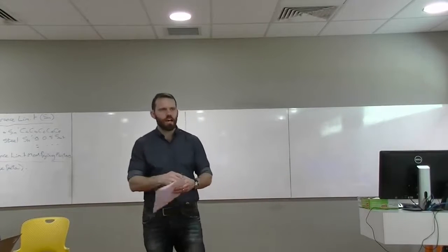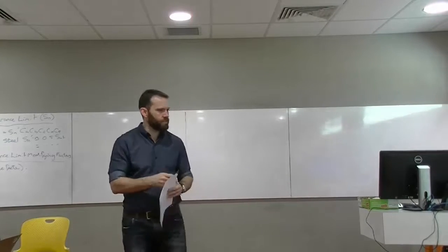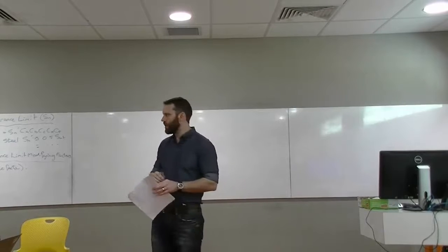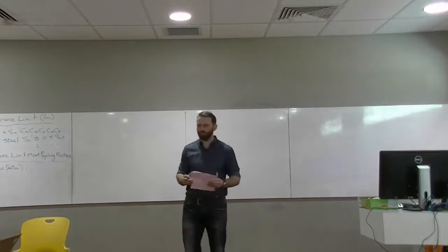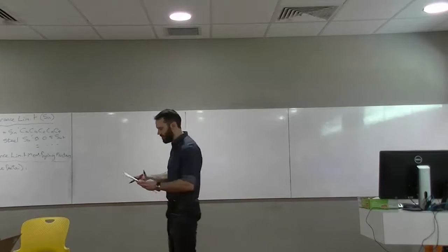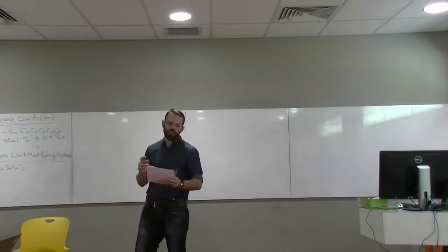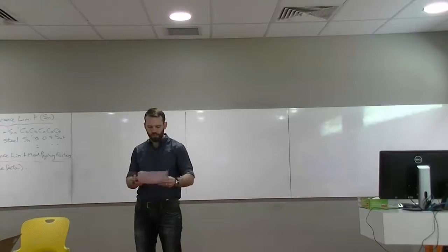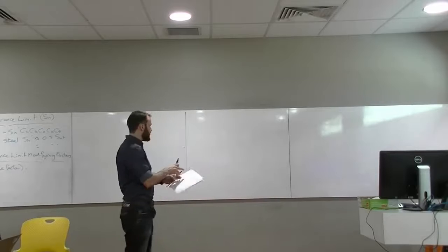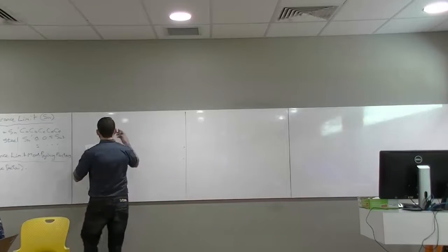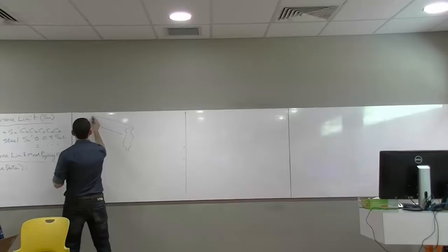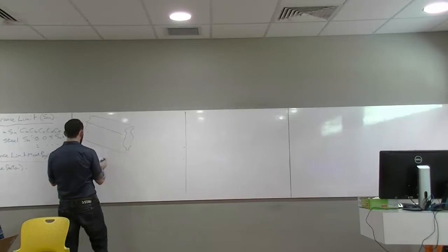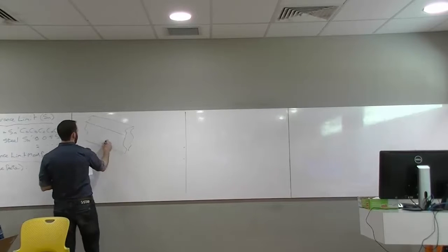Alright, so in terms of layout, and to save time, because obviously you've already done this, I'm going to assume that you've got an assumptions section, whereby you assume a couple of different things, weight being negligible and so forth. And then I assume you have a free body diagram, shear force diagram, bending moment diagram, and a stress element identification that might look something like this. And what do we got? We got tension at the bottom, so I'm just going to analyse the bottom element like so.